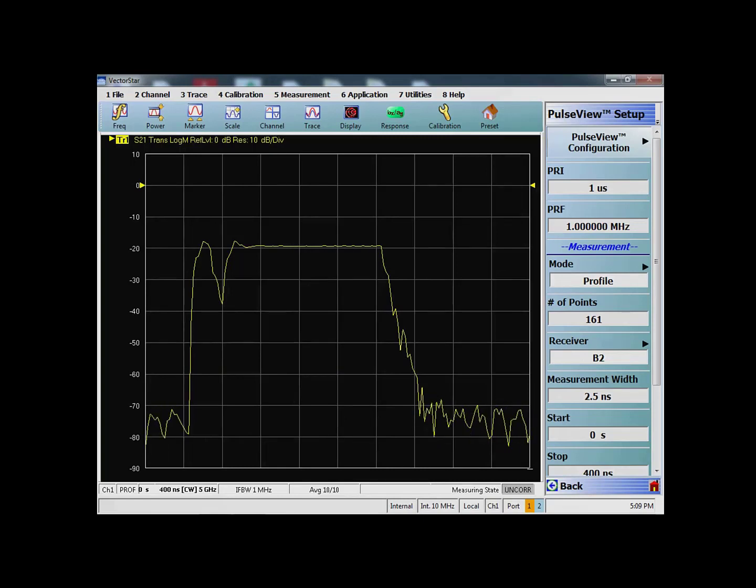Now here is something that you will see: there is a lag here. Although we started the pulse at 0 nanoseconds, this lag is basically because of the switch inside the pulse demonstration module. Because of the switch, it takes some time to switch on and then to switch off. That delay is because of that. We can put a marker, and it's roughly around 35 nanoseconds. But again, that's not important. It's important how finely you can resolve